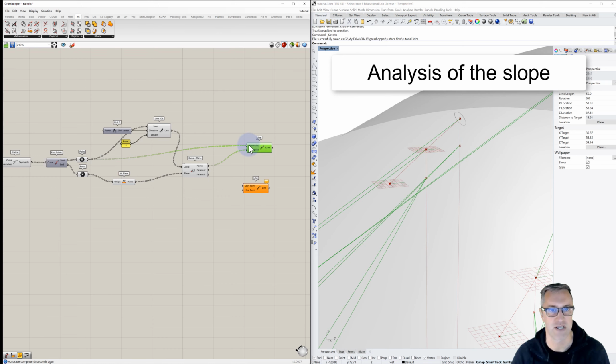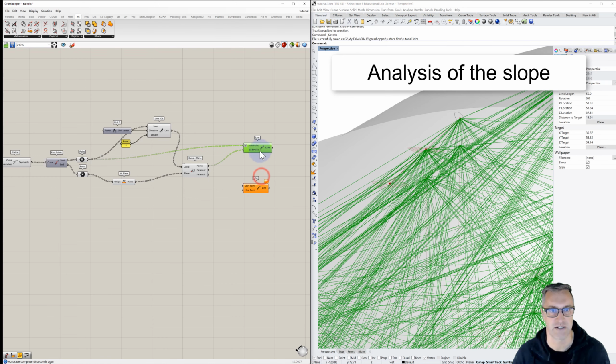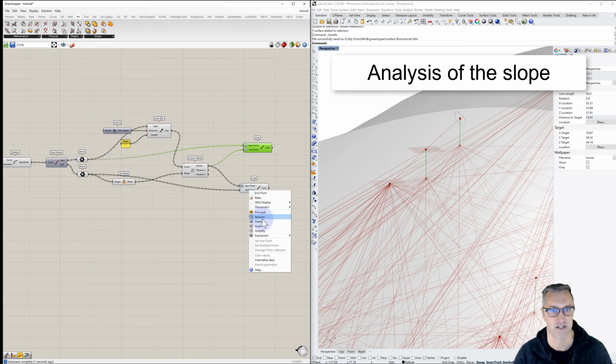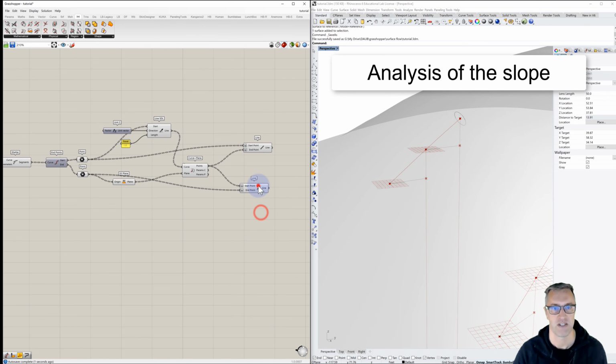And for these lines, we do want to flatten this down. Now as we click on this line, we can see we get a vertical line and a vertical line. That's good. The next thing that we want is to go from the end, which is going to be our end point, and the start point is going to be from that intersection. We need to do the same thing. We'll flatten and flatten. And now these are the horizontal lines.